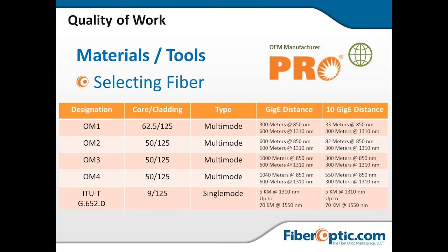And what I want to illustrate here is the jump that happens when we go to 10 gig, the distance that we get at 10 gig. So if we have a 62.5 today, and we're operating at, let's just say 250 meters within the spec or the threshold, we're fine.